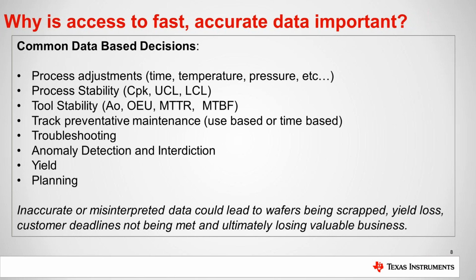How have I been, say, depositing material over the last month? After I did the PM, did it shift? If I'm out of control, how do I bring it back in control? Also, we look at our Cpk, which is process capability. We have some say in our upper and lower control limits. Our ultimate goal is to try to narrow our window on where our process is running. Our spec limits are set by our device and our customers' needs and applications.